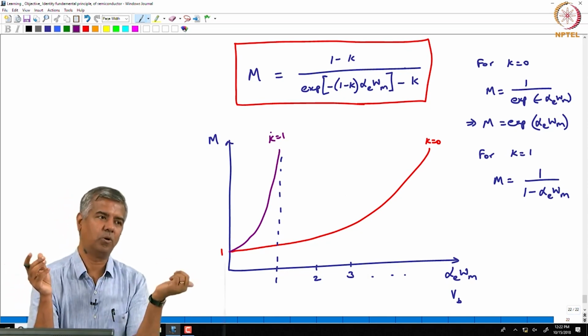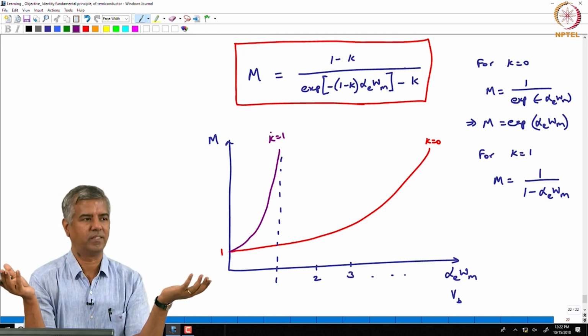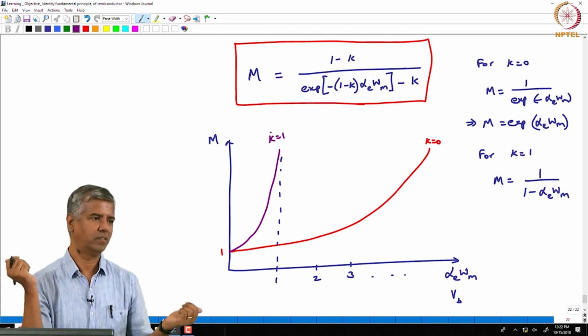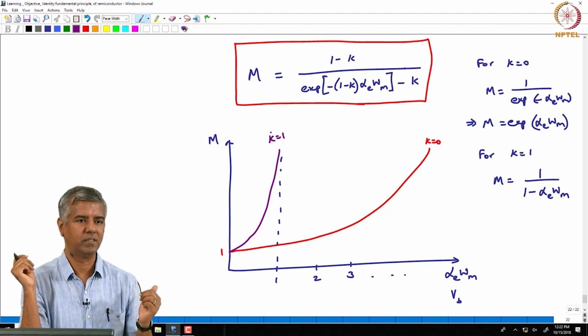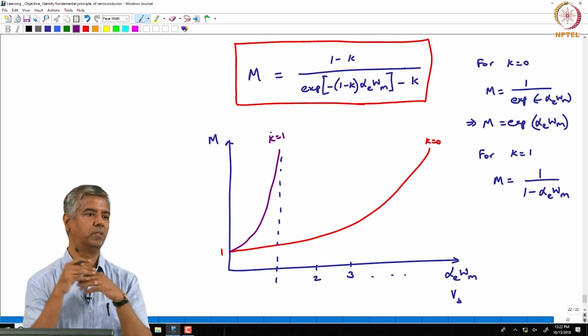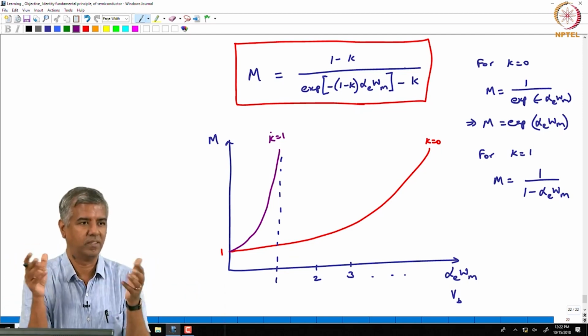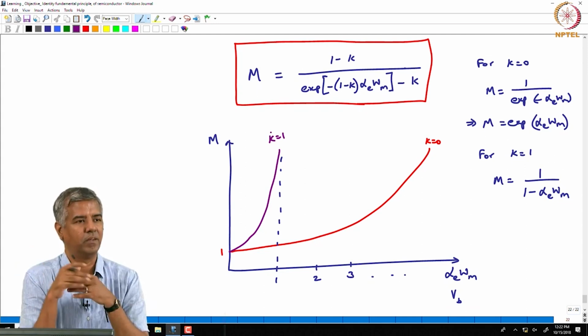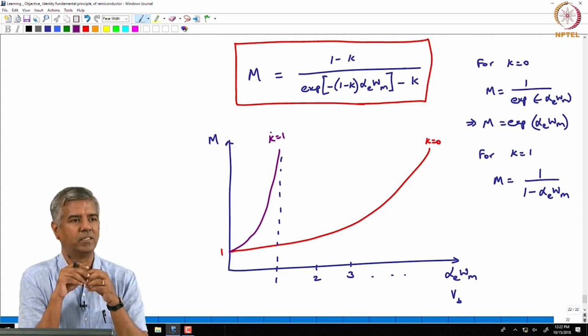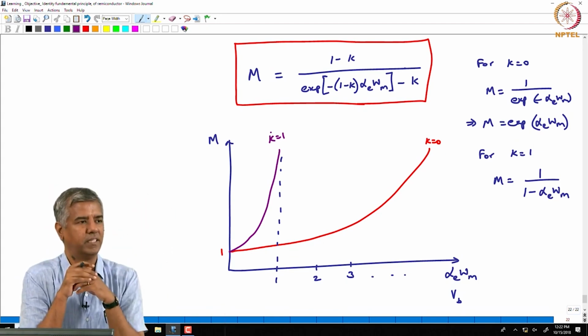Now, if you do it with holes, it becomes even more noisy, because those are two different independent processes in terms of creating that avalanche. Okay. So, you have much more noise, much more chaos essentially happening when you have both of your carriers generating avalanche independently. You have a question?